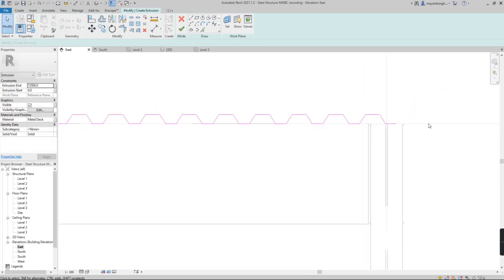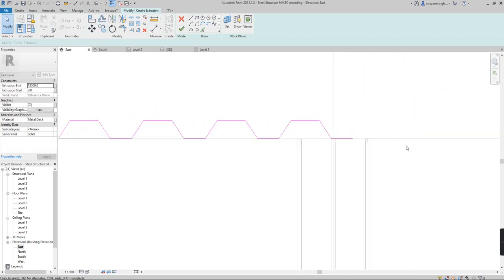Okay, now we are going to first go to offset and create a 1 mm offset. If you don't have it, do it, and then click somewhere else. And now what we're going to do is select all of this and create a 1 mm offset on the upper side. 1 mm is the thickness of the sheet, right? So how do I select all of this? Press tab once, everything is selected, press OF.